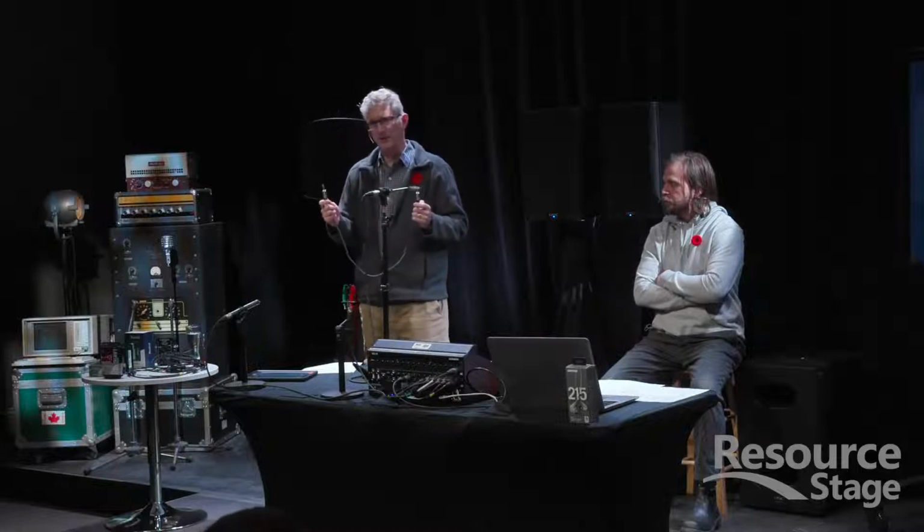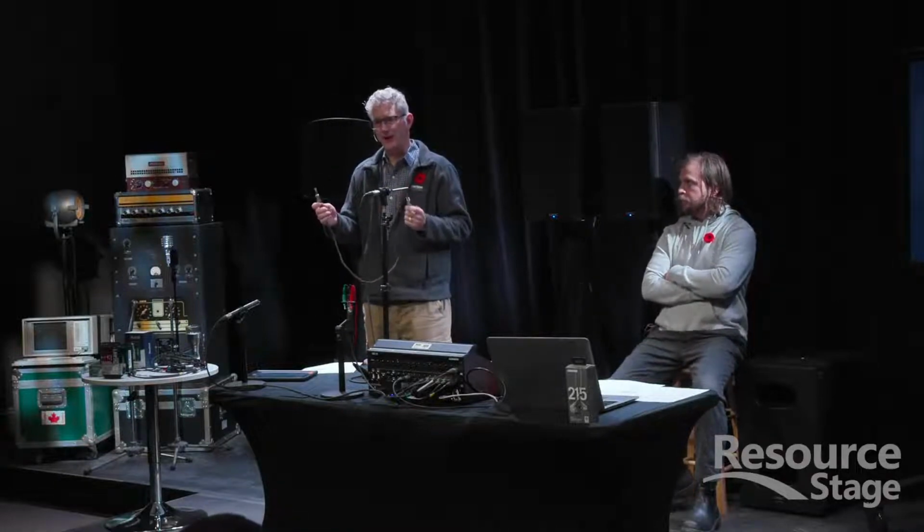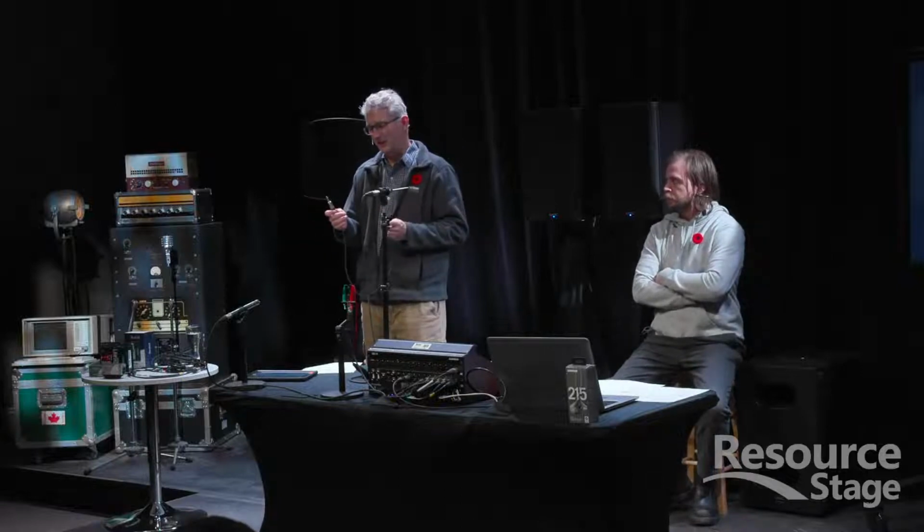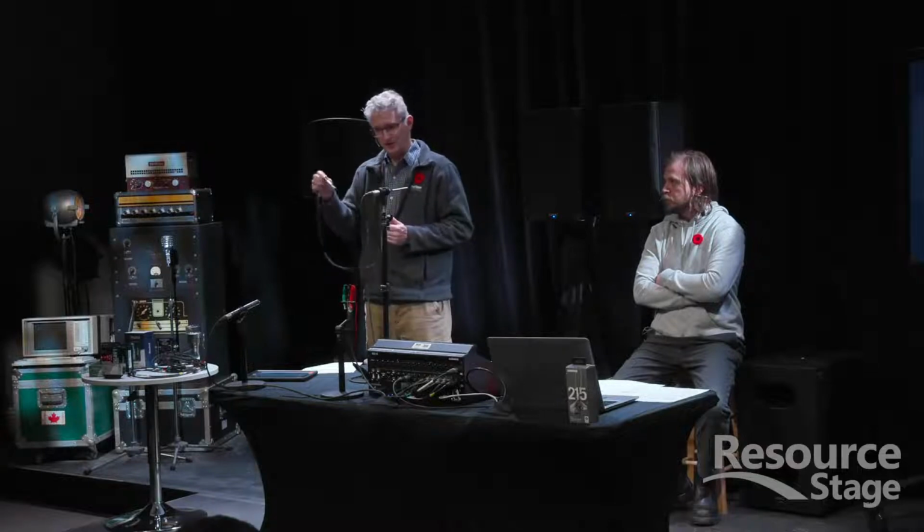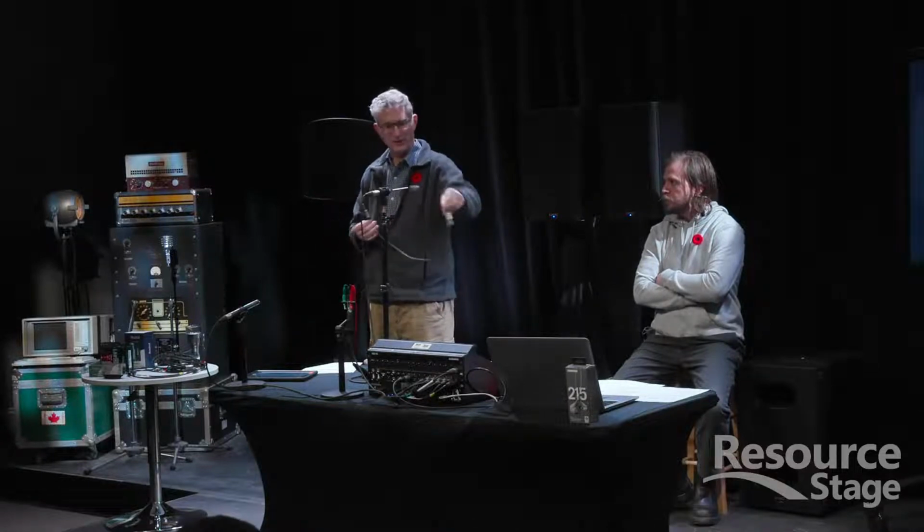You want to be careful when you say, oh, I've got this piece of equipment that has a stereo output, plug this into this, and then, oh, I'll just plug this into my 1/4-inch connector on the mixing console. That's not going to work very well because the left and the right are going to come into the mixing console and be connected to your differential amplifier, and it's going to sound really bad. We're going to talk about that a little bit more in a minute.